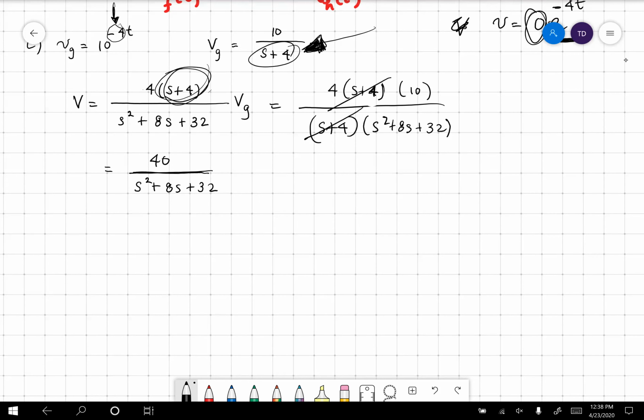Because the power systems that we use to power homes and buildings and everything else all operate on 60 hertz in the United States. And there is a lot of 60 hertz noise that gets picked up on lines that act like antennas. So a lot of times we have to filter them out. And so we build filters that filter out 60 hertz signals because they are all over the place, especially when you're dealing with very, very low signals. And we're dealing with low signals in the world of communications all the time.